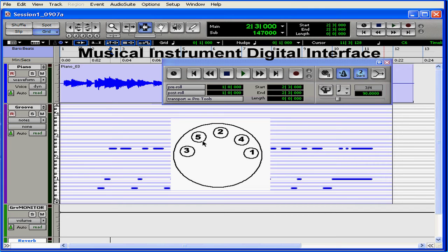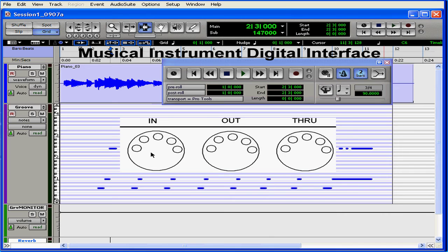Because MIDI data is serial data, meaning that the data events get transmitted one after another, not at the same time. So basically all you need for data transfer is a single connection, but you need a cable for each direction, in and out. One to send information and one to receive it. Because one MIDI cable can only transmit data from one device to another, most MIDI gear have 2, if not 3 ports. Most MIDI instruments and sound cards these days have a MIDI interface that looks like this.